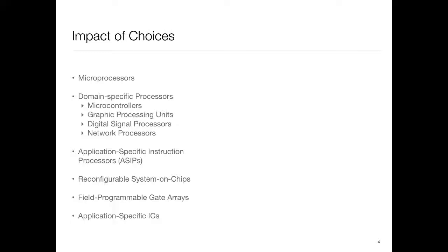But then oftentimes you face the thing that, I still need a processor. So there are so-called soft processors, which are processor cores that you run on the FPGA. So now you have an FPGA on which part is devoted to implementing, let's say, a small ARM processor, and the rest of the FPGA is used to implement the hardware logic.